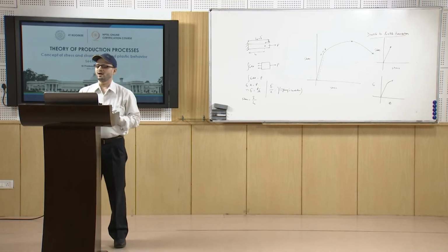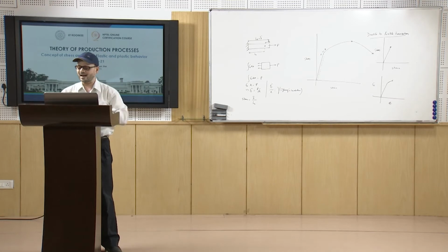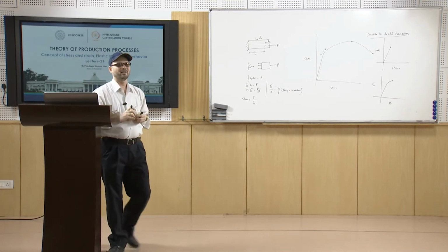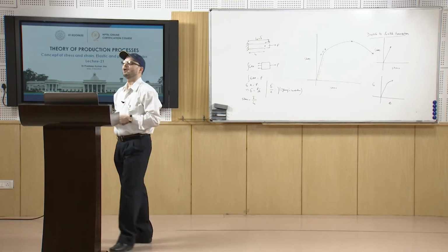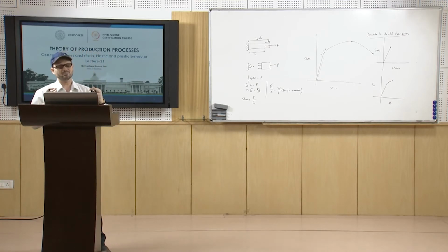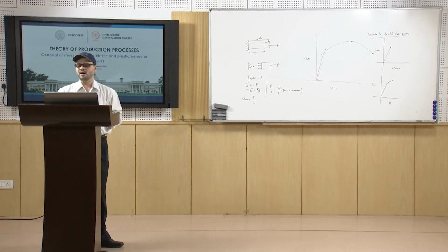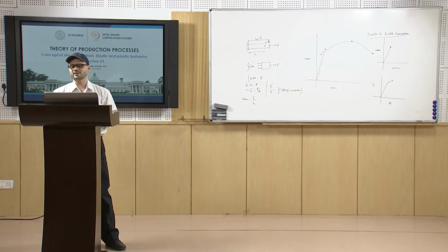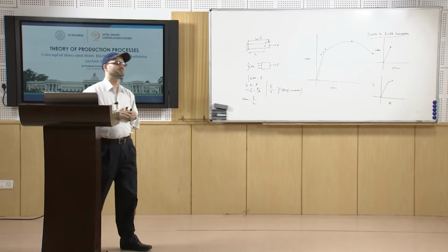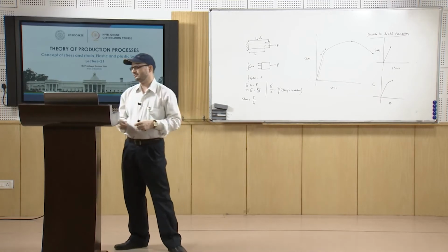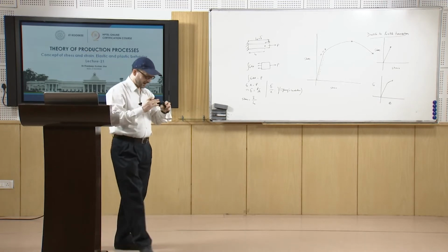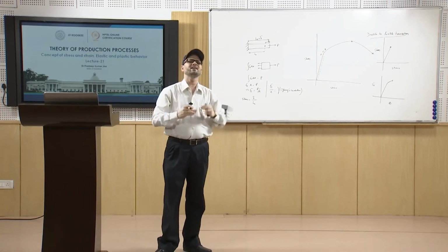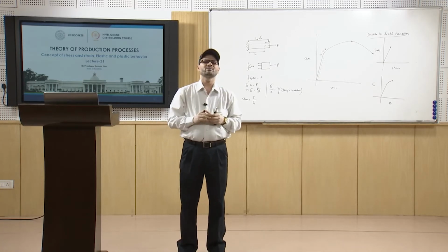Normally, if the material is statically loaded at a very high temperature for a long period of time, then this type of fracture, known as delayed fracture, occurs in the material. Depending upon the stress and temperature conditions, there may be no yielding prior to fracture, and the material will basically fail. In the presence of hydrogen, it has been seen that steel fails, as an example of delayed fracture. In this way the failure occurs in different kinds of materials.